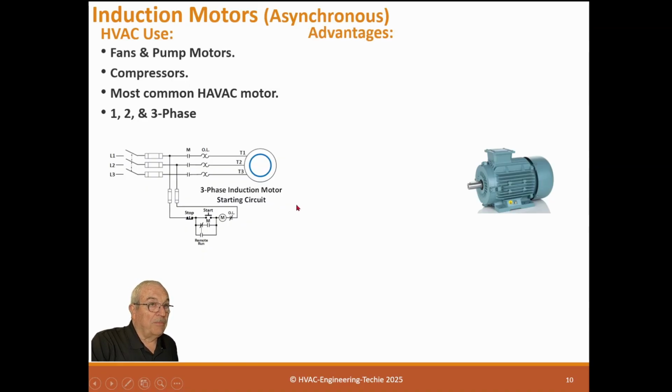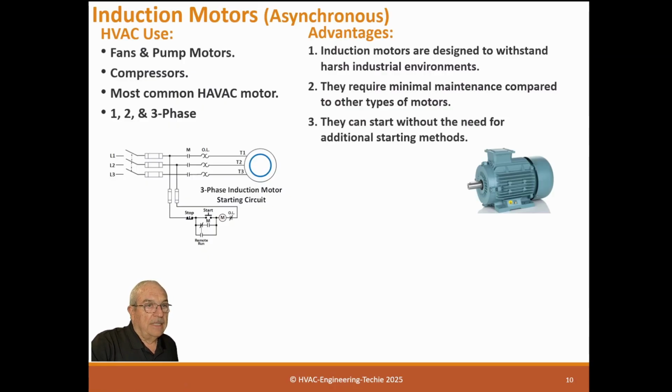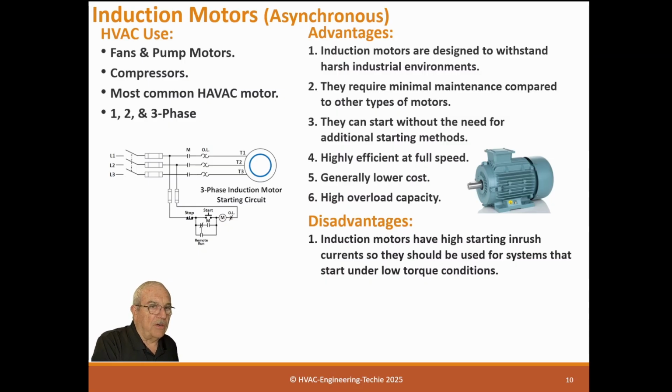They start automatically because of the magnetic field circulating. Induction motors are designed to withstand harsh industrial environments. They require minimal maintenance compared to other types of motors, no brushes, so you don't have to worry about that. They can start without the need for additional starting methods, true. Highly efficient at full speeds, but not at low speeds. Generally lower cost motor, higher overload capacity, true. Disadvantage: induction motors have hard starting and inrush currents, so they should be used for systems that start under low torque conditions, like a fan.